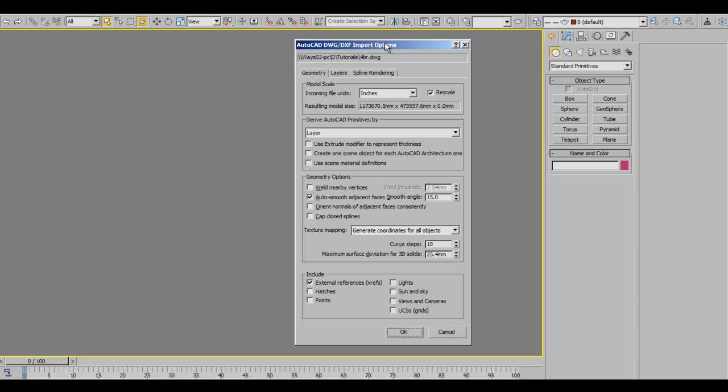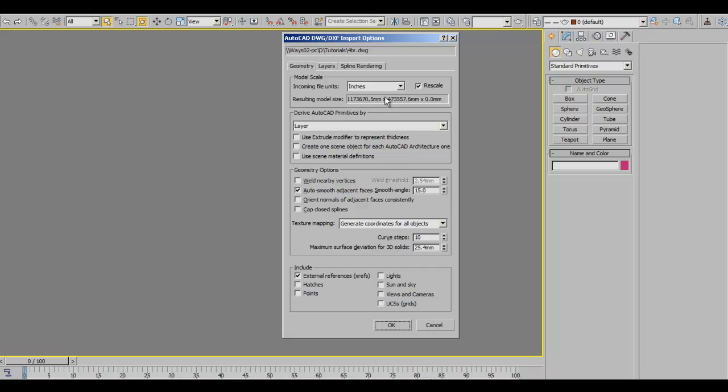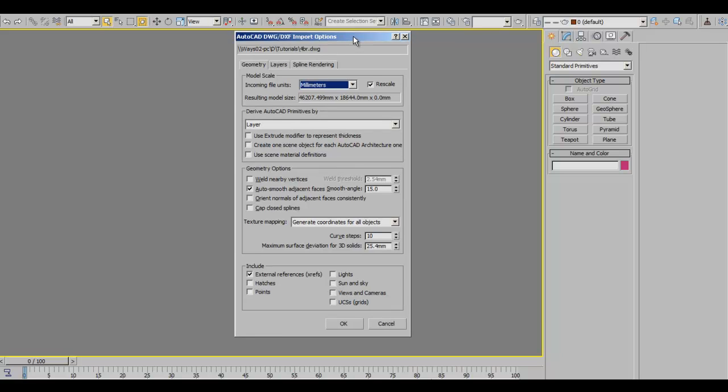I would recommend, because right here in this part of our country in architecture we work with millimeters, that we work with the metric setup, then metric scaling units. Then I set it up as millimeters. If you have a very large scale site, I'd recommend you come in with meters, which is still very good, and due to our metric system, it actually helps scaling in your object, in your scene.